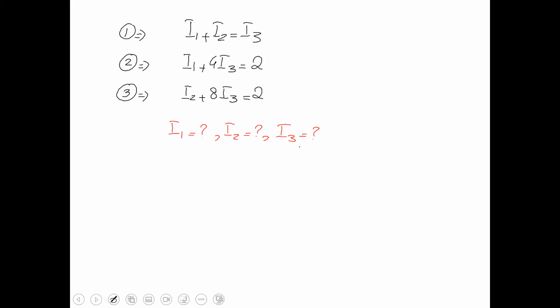Now we have three equations. I have summarized them here for you. If the examiner says, you should remember that in our O-level maths, we can solve equations, and also in a calculator, we can solve it. So these are the three equations. How do we solve it? We put the first equation into the second, because we have to replace I3. Once we replace I3 from the second equation and the third equation, we can solve them simultaneously.